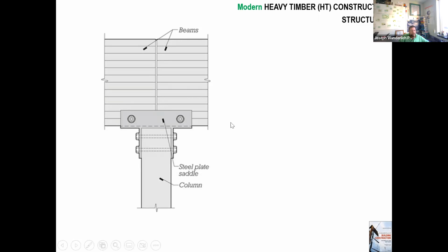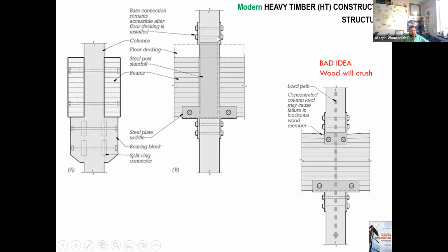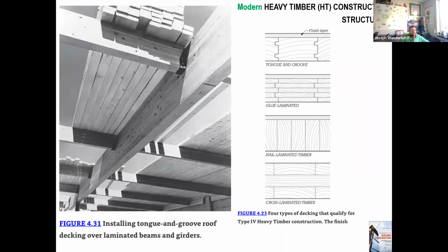So this is how you have a column and two beams come together. Well, what about then going up a floor? Well, don't rest something like this on the wood. The wood will crush, especially if it weathers over time and moves around. This is a bad idea for transferring loads. So this is just something that an engineer, after enough years of practice, would know to do. They're doing that for a living.